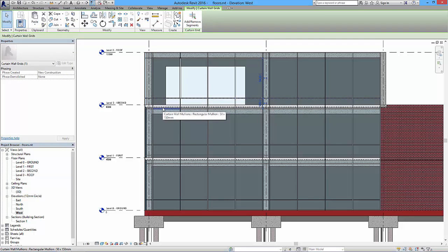So I've got the grid line, and this is a tricky little maneuver, so you're going to tab in again until you pick up the other grid line. So I've got that as well. So that's already one selected. To add to the selection, it's the control key. So I'm going to click and add the two. So I've got both of them selected.